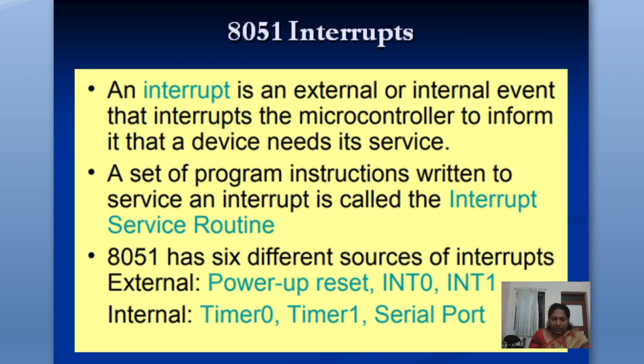So when an interrupt occurs, the program has to stop, go find out what is there in that interrupt, finish that program, come back. It is as simple as that. When it goes to a particular address to do the work of that interrupt, you call it an interrupt service routine. These are terms which you need to know, because we'll be talking in terms of the technical names. So interrupt service routine is a program which is written when an interrupt occurs, and that program is available in some location. If the location is mentioned, it is called vectored interrupts. If it's not mentioned and you have to find out the location, you call it non-vectored.